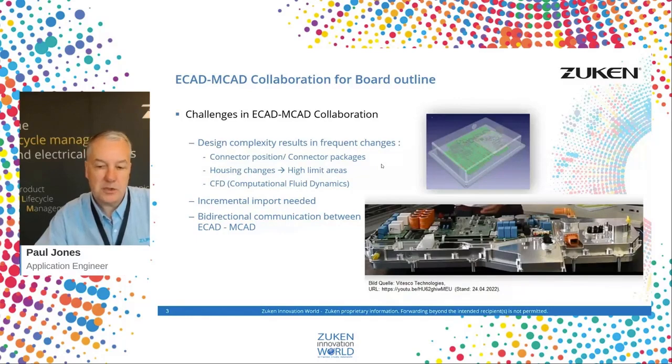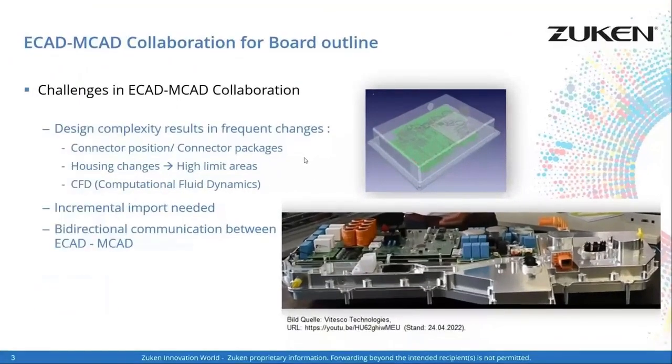And then also, if you see the image on the bottom right here, you can see it's quite a complex housing. There's a lot of metal work in that, and with that, you can probably estimate that there's a lot of heat. This is where CFD comes into play as well, because what a lot of mechanical engineers do now is simulate airflow, for example, on the products. What they will then see is that you might have to have certain channels for the air to cool certain devices down, and also where the air is going to escape.